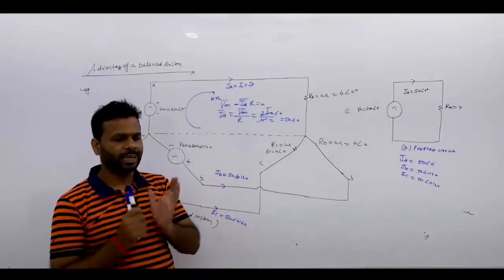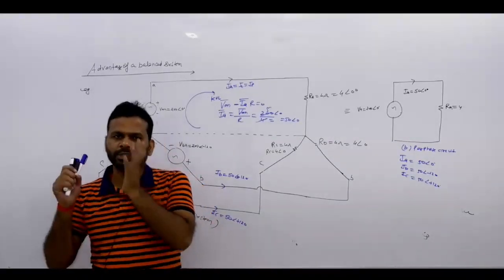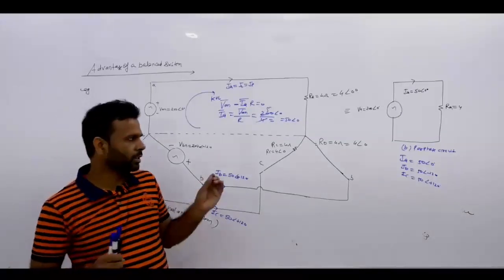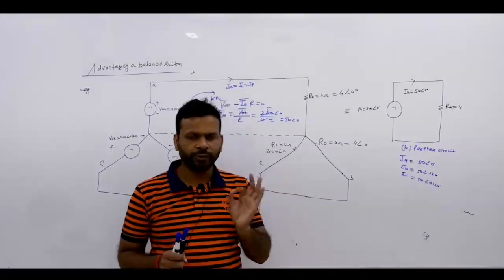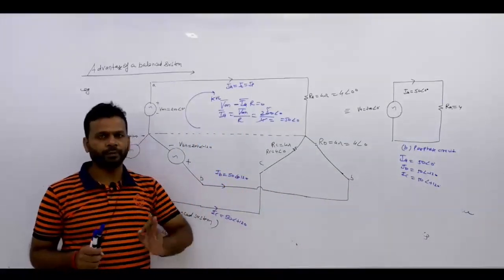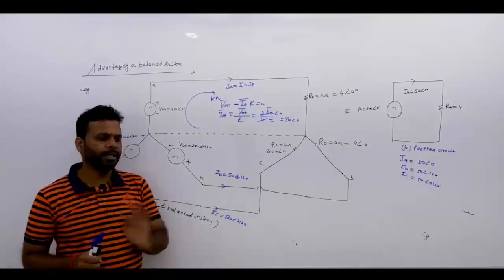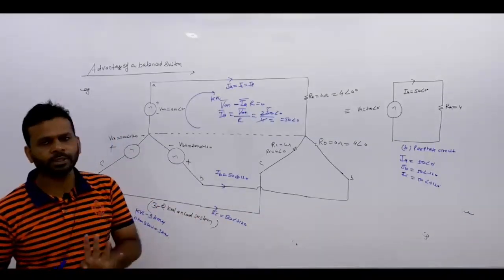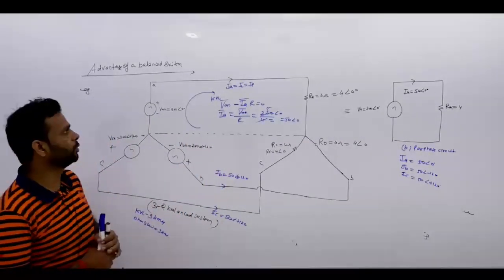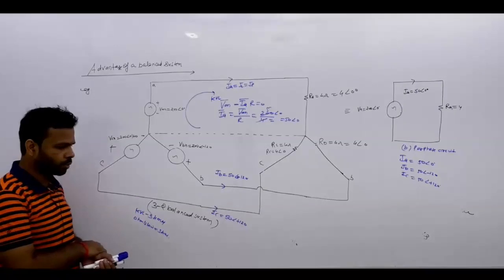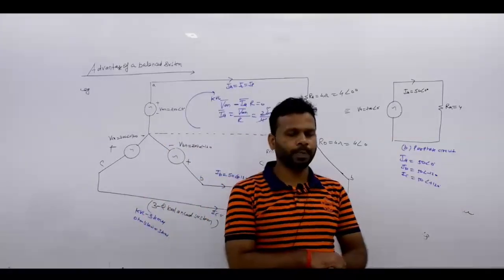Because while drawing the three-phase system or three wire three-phase load, it takes much time. It is complex. So all this complexity is reduced by the per phase system. So in general, all the three-phase balanced systems are shown by a single phase system, because it reduces the complexity of the network and it gives complete information about the three-phase system by having only one phase system knowledge. Okay, so this is about the balanced and unbalanced load and the advantage of showing a three-phase system by a per phase system.